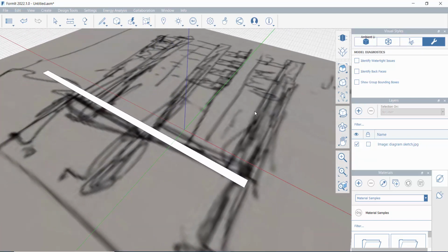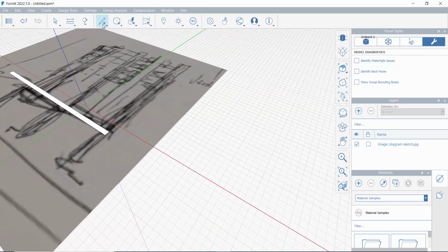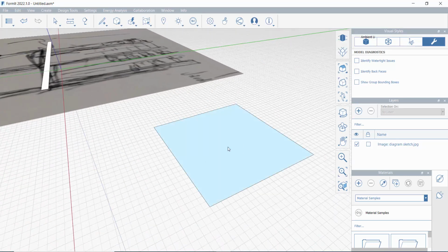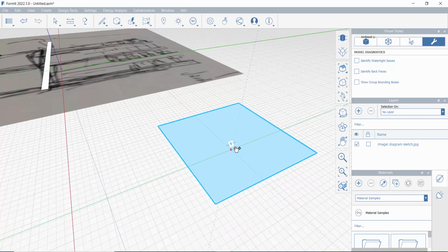A solid two-dimensional polygon. Now, let's talk about polygons really quick. If I come to the side over here, I'm going to use another method, a 3-point rectangle. 1, 2 clicks. Okay? That is a solid infilled polygon. What I mean by that, I can select all of that with a double click, and then it immediately wants to let me move it.